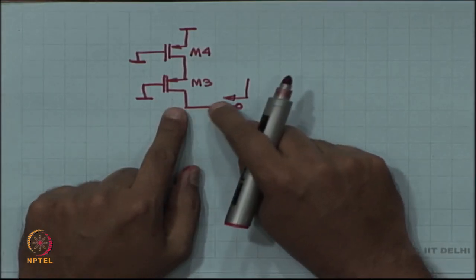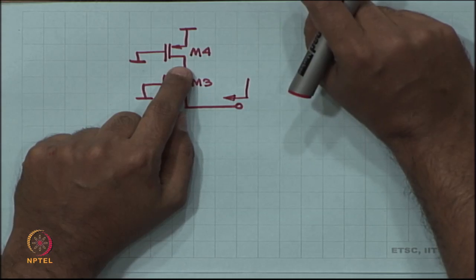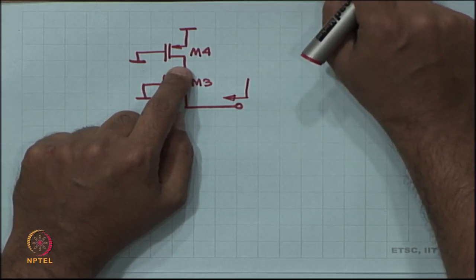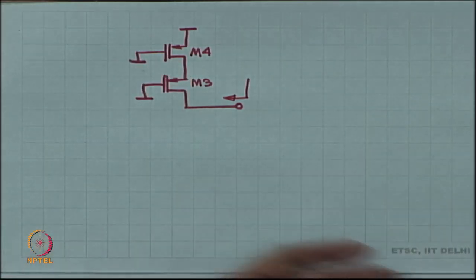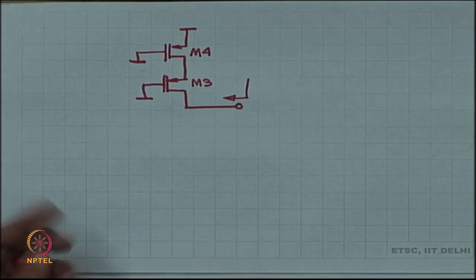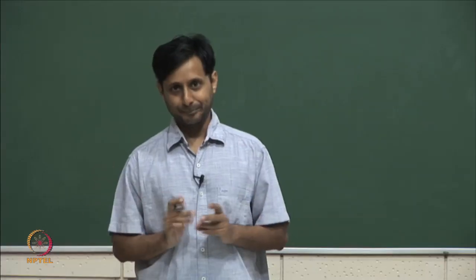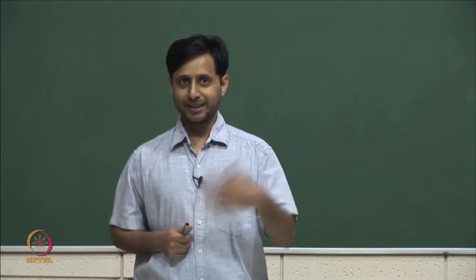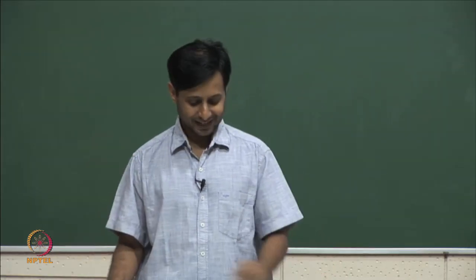This MOSFET is going to behave just like a resistor, rds4. The small signal picture of the NMOS and the small signal picture for the PMOS, terminal for terminal, is exactly the same. There is no difference. Do not interchange the arrows, do not make them opposite. Terminal for terminal, it is exactly the same.